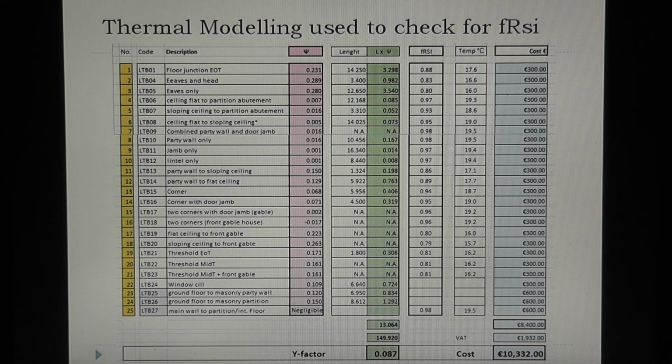The 300 is generic. I've got no quotes on this, but it basically would allow you to do a baseline analysis of the existing junction to see if it needed to be upgraded, and then maybe 2 iterations of different levels of insulation to see if you had achieved the most cost-effective means of upgrading the junction to meet the minimum FRSI, the minimum surface temperature required.